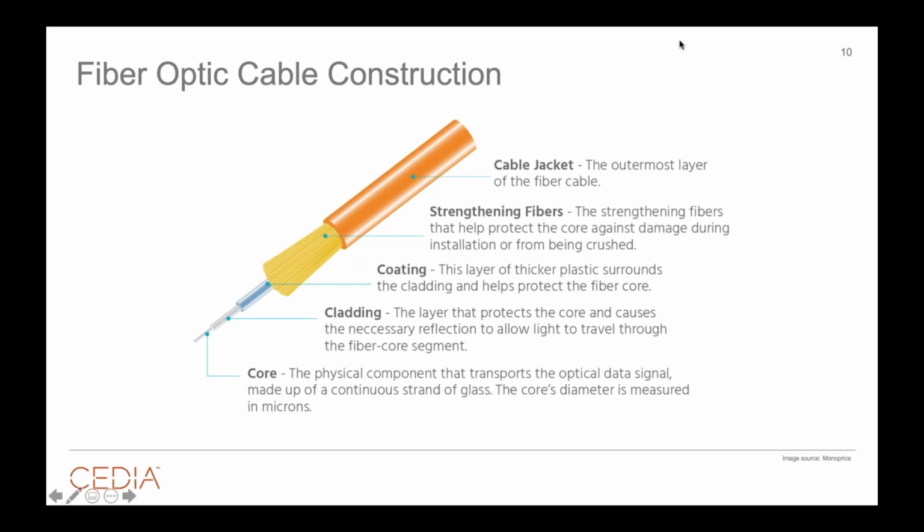You'll see armored fiber optic cables, a lot of different technologies around the jacket and the different pieces and parts that affect the jacket. But it's once we strip that jacket back that you start to really know you're dealing with a fiber optic cable, because fiber has strengthening fibers. And in most cases, from most manufacturers, those fibers are made with Kevlar. Same thing that you're putting in bulletproof vests, you're putting inside of these cables. Even these tiny little 3mm cables, they have Kevlar yarn inside of them. That's what gives it its strength. And when you're pulling fiber, you want to pull by that Kevlar, because that's what's going to deliver 100 to 220 pounds of pull rating, the Kevlar yarn.